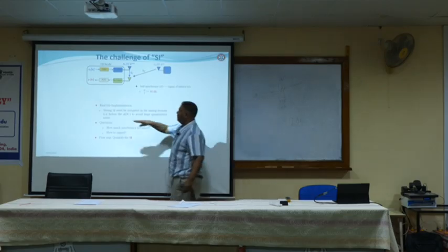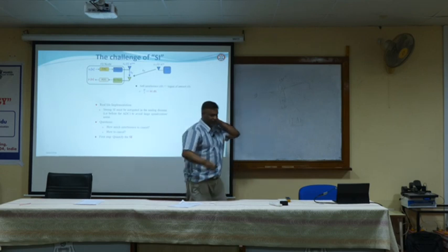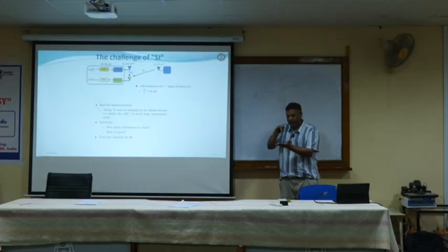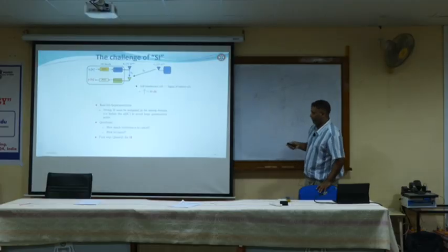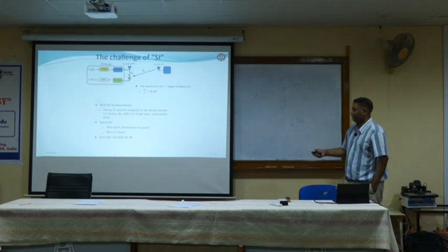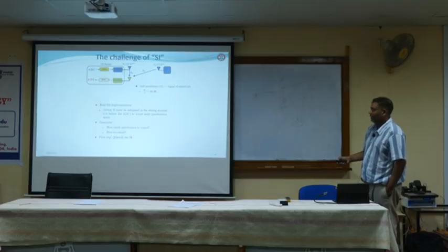Then we do the remaining self-interference cancellation in the digital domain. We need to bring the self-interference below the saturation region of the receiver. To do that, we need to do analog domain cancellation before the analog-to-digital converter. How much interference needs to be canceled, and how do we cancel it?